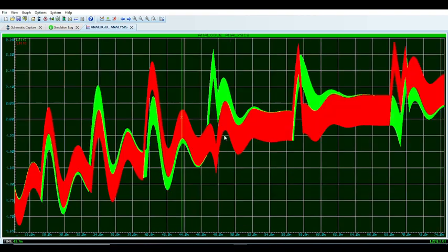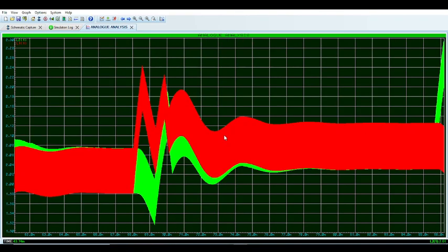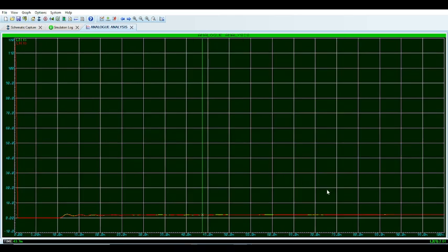So as you can see, obviously, it doesn't quite get there to 2.2, but it gets close. But that's why you want a controller with better PWM resolution, because then you can get closer to the value. So essentially, to get to the perfect set point that you want, if you have a set point of 2.2 and you want to get to 2.2, you need a combination of a high resolution ADC and high resolution PWM.